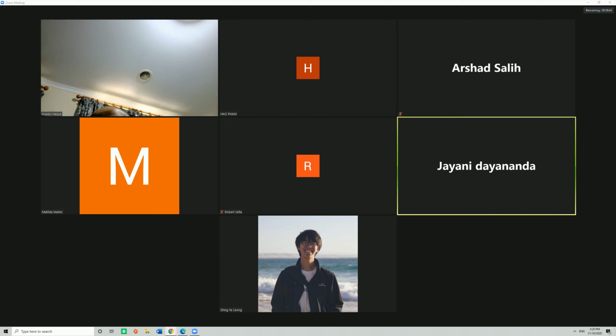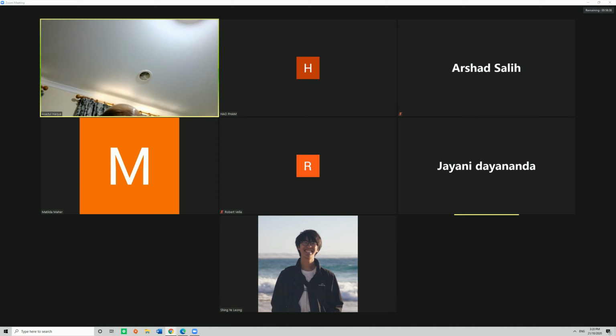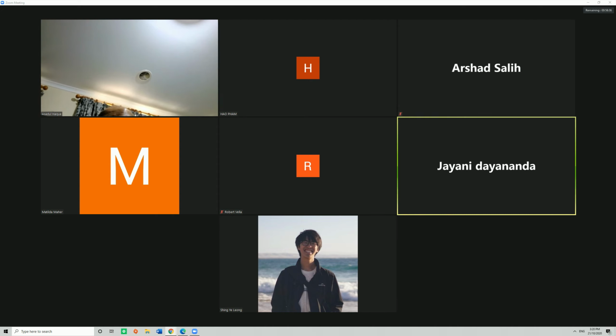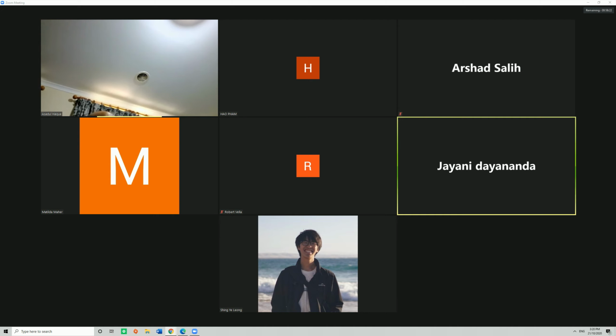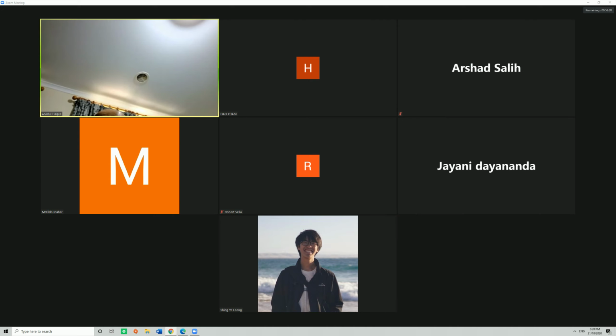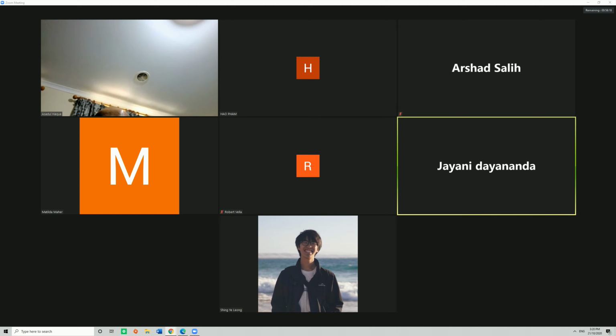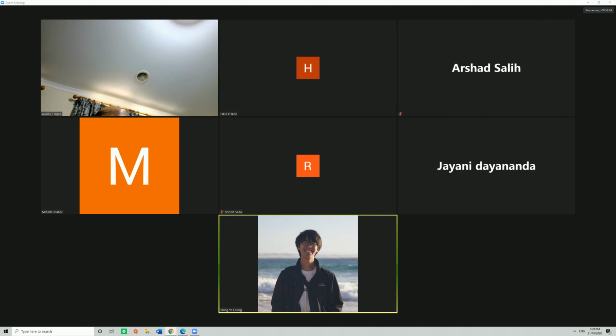Yes, I just have a question. For this, when we're checking the structural, just for the load, are we always using the unfactored load? What did we do before? You remember we checked structural ULS before, isn't it? Yes, it's 1.35, and then for the negative skin friction it's 1.2.